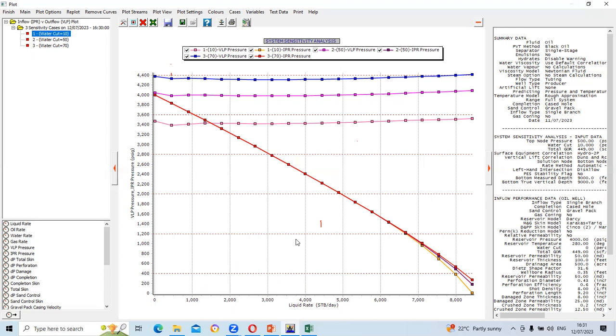Where is the water coming from? So you have to analyze it to get all of that. It may be from the aquifer, it may be from water coning, which I explained yesterday. It may be from flow behind casing, it may be from channeling. So there are different causes of water.